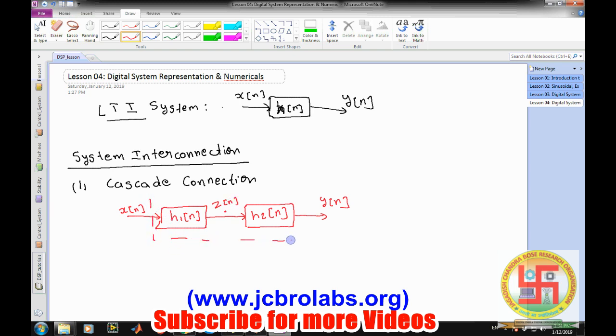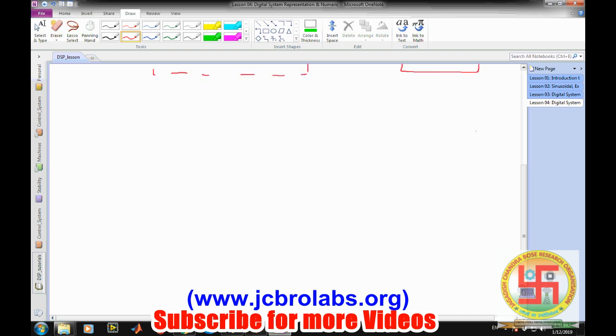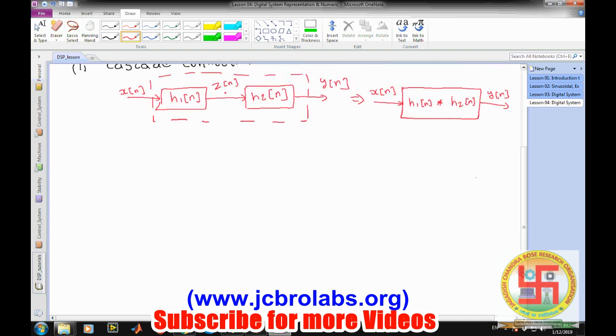This entire system we want to represent by a single system. As we discussed, the output is h of n convolved with x of n. Here we have two systems, so it will be h1 of n convolved with h2 of n, with y of n as the output and x of n as the input. This is the first connection.